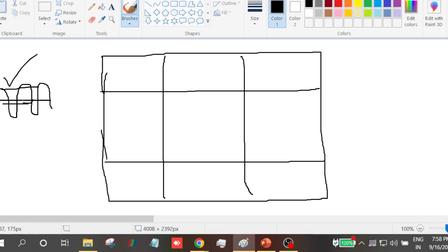And then we might end up, although the equations satisfy this discretization scheme, with the physical reality and the numerical results far away. Zero we get. This is not exactly this, right? But this also satisfies the Navier-Stokes equation. But it is far away from the reality. So that is why we have to use the staggered grid, to capture the oscillations in the pressure.